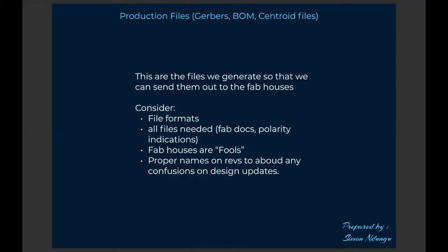So what do we consider here? You already know your manufacturer, so you have to know the file formats that they need, all the files they need. Do they need fab documents? The fab document should indicate the polarities, say of some capacitors and LEDs. Those are light emitting diodes.